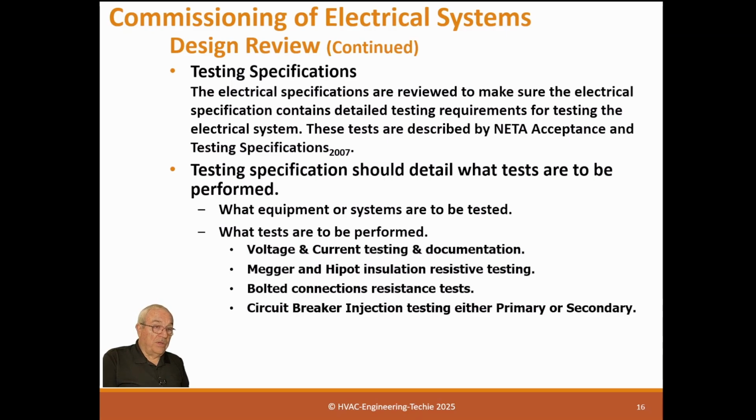There is another way to do that, and the reason is the manufacturers say that primary might actually damage the circuit breaker, because when they do it at the factory, now all circuit breakers are tested at the factory, but it's done under sterile conditions. It's done at a certain temperature. It's done at a certain humidity. It's done at very close tolerances on the power. Doing it in the field, those conditions are not there, so it may actually damage part of the circuit.